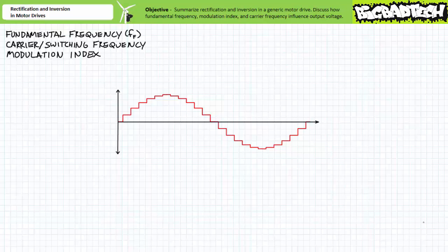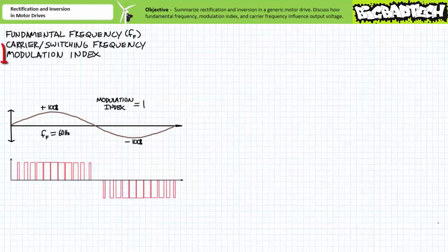The filtration circuit removes any unwanted electrical noise and voltage spikes. However, it does not do so entirely. Motor drives are notoriously electrically noisy and can sometimes induce unwanted harmonics and voltage spikes if not properly shielded or installed. Moving on, the remaining property, modulation index, influences output magnitude.